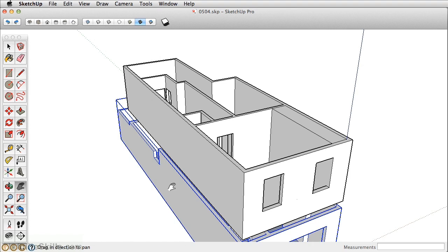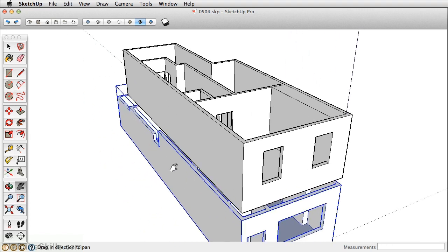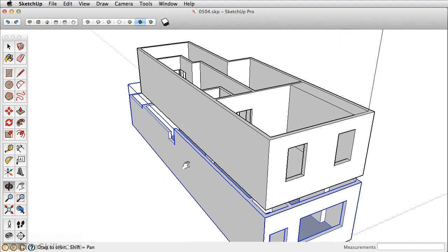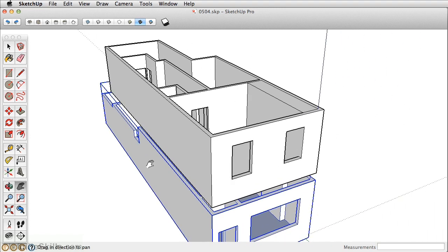When I press H right now, our keyboard shortcut is the pan tool. That really doesn't make much sense because I use Orbit plus Shift to pan. And H is a close key for my left hand, so we can make that H to be hide. And for hide rest of model, we're going to make it Control H. That'll make sense in a little bit.